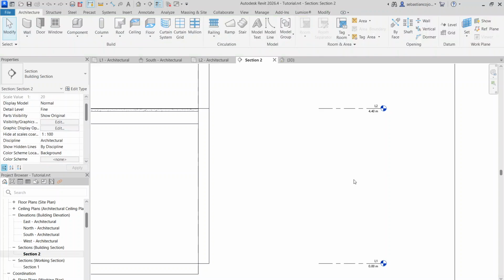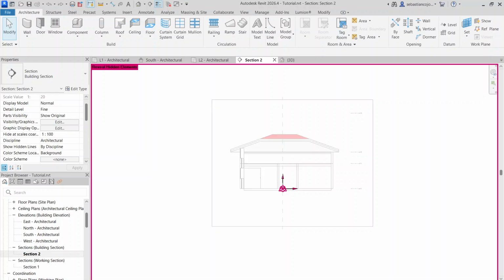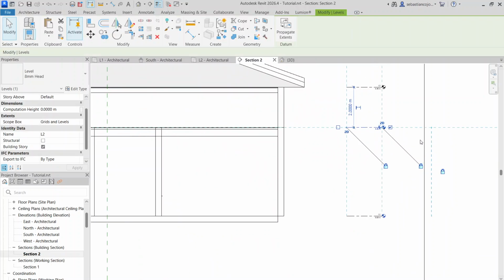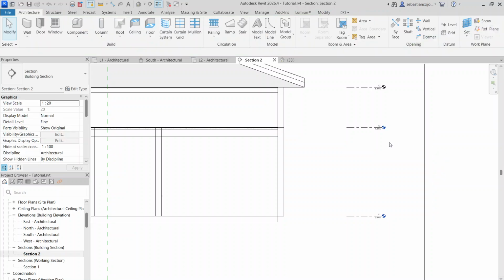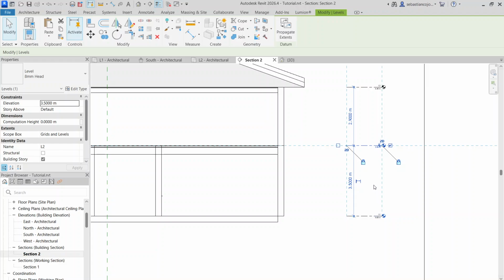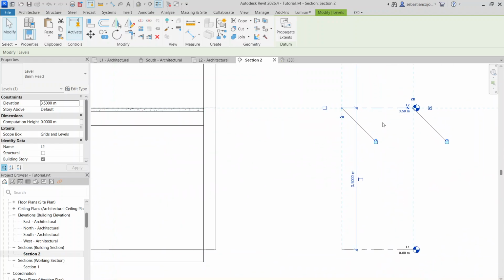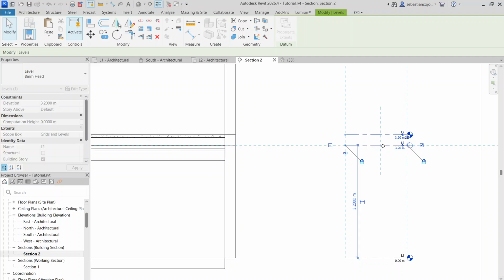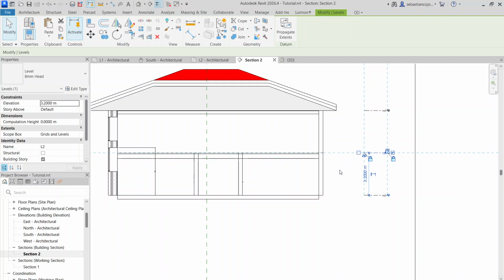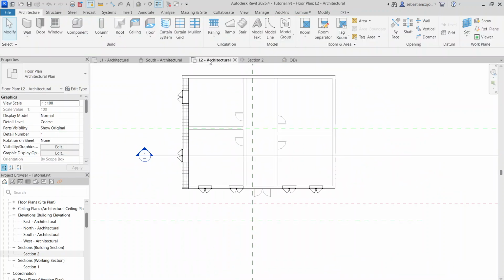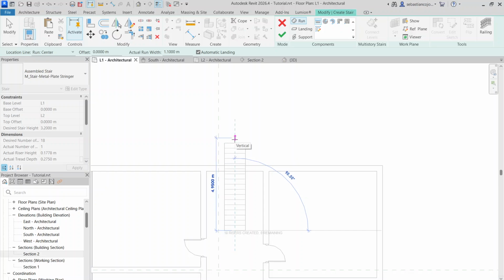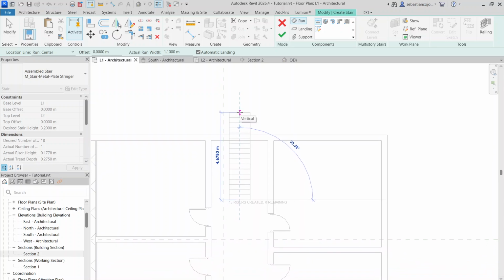Something does not adjust well in the height section. I had a constrained height, and that was causing the problem. I had something locked, and yeah, that was causing problems. Careful with these. Now we have the right height, and now in L1 we can check the stair. Yeah, we have less stairs. We have like 18 stairs. That's more reasonable. We had 25.